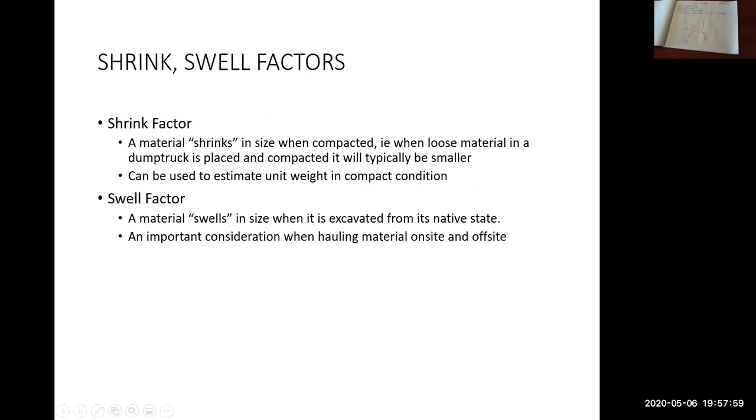So here we talk about that shrink swell that I just mentioned. So shrink. A material shrinks in size when it's compacted. So when loose material in a dump truck is dumped out of the box and placed into a hole and it's compacted, it will typically be smaller. So the volume that's in the box, if you compare that to the compacted volume in the hole, the volume will be less than the volume that was in the dump truck box.